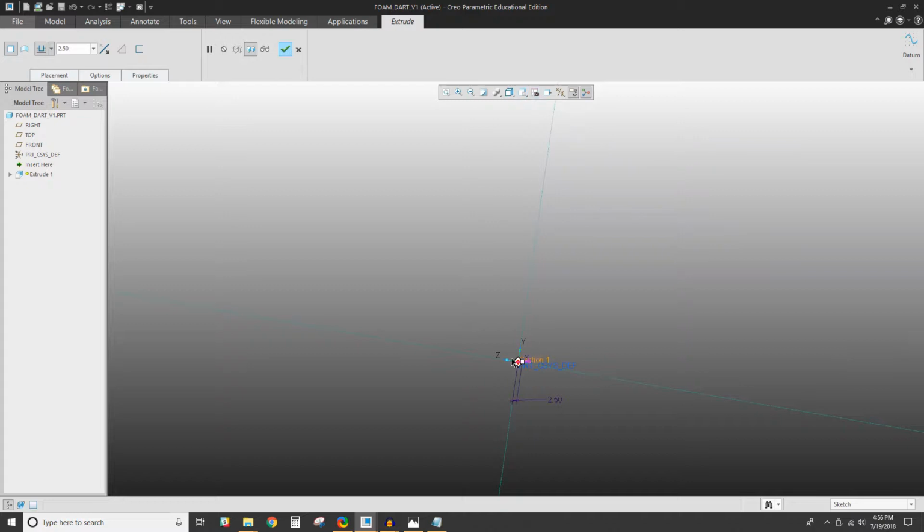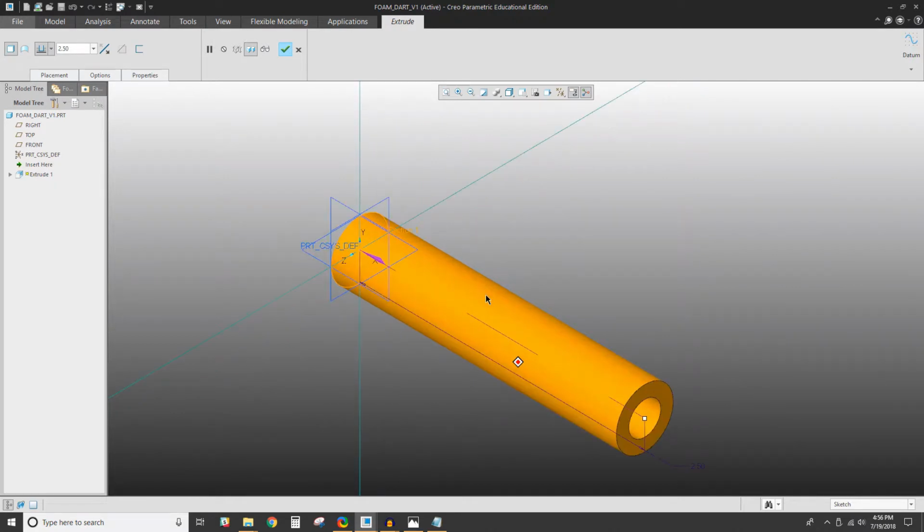And if it disappeared like that, this is your orientation and view bar. So you click on saved orientations, it's the cube with the little checklist next to it, and click default orientation, and then zoom in like that. You zoom in by using your middle mouse wheel and scrolling it towards your hand.